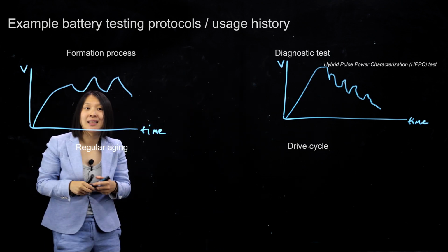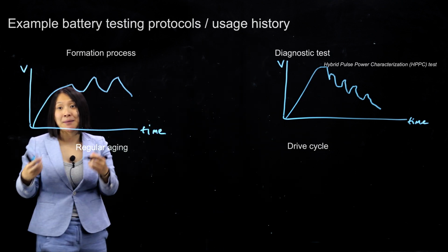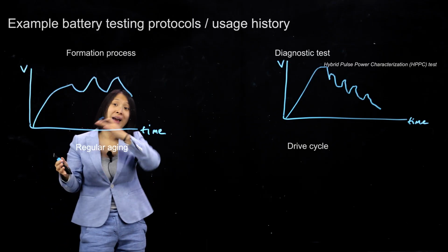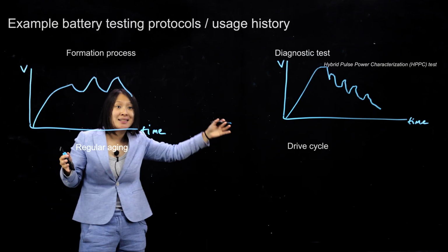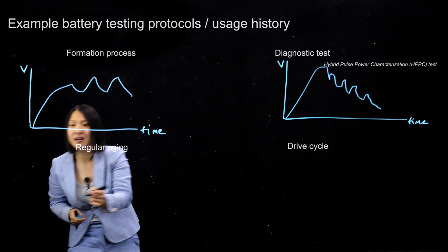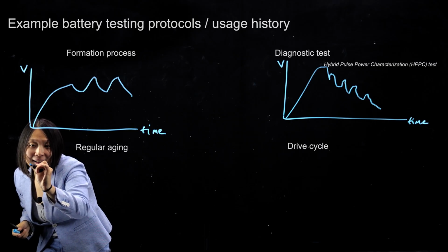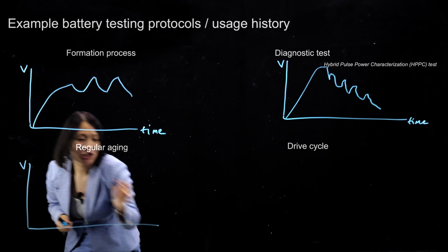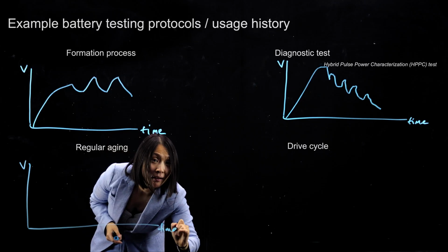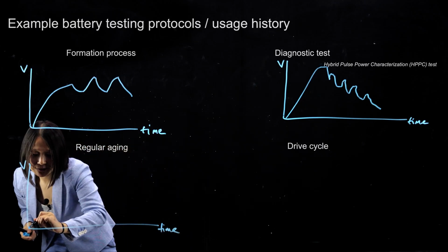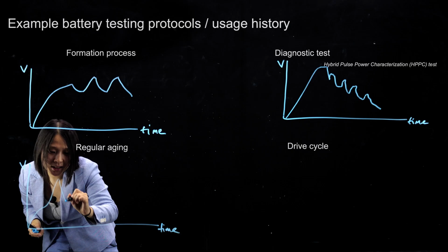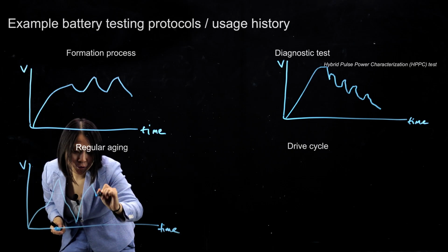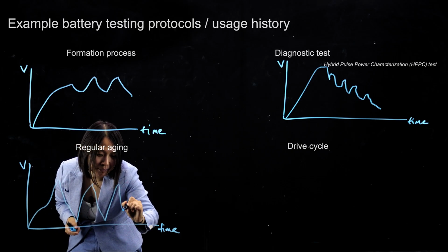Of course, just as we've been discussing, typically in a laboratory environment, we can perform controlled cycling tests to test their aging behavior. And if we draw, again, the voltage and time curve, you may see that as a function of time, we apply some voltage, and then they form regular charge and discharge cycles.